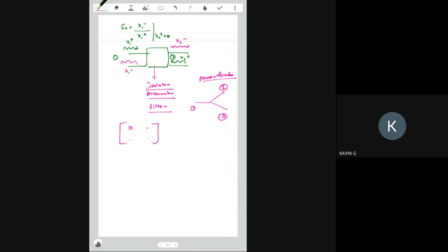I don't even need to actually test it experimentally, because when I get this device, the manufacturer will give me the data sheet of the S parameters; they will give it basically. So with that I can 100% make sure that it is perfectly matched. Okay, that input port is perfectly matched. That is a more useful advantage of having the S parameter values. So that is one thing. And okay, how practically will they give the S matrix?